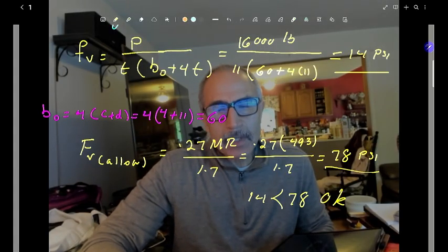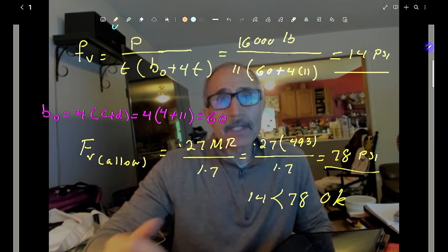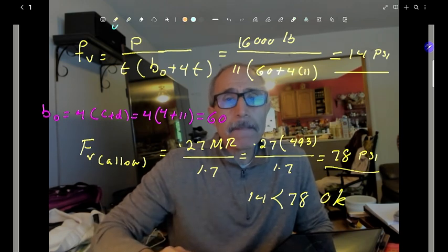There are different ways you can calculate the thickness for the slab on grade. The easiest, the best way was using PCA. But if you ever want to do this at a professional level, make sure you have ACI 360-10, and there are a lot of good examples and different methods there. Check for all the criteria that I had on the PowerPoint. Let me bring that up. I want to show you.